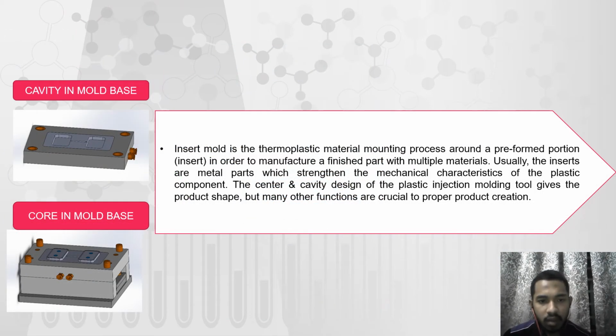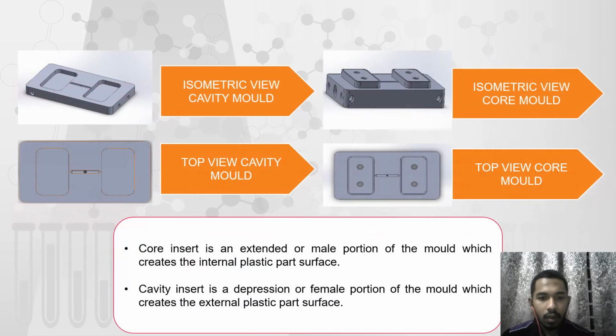Cavity in a mold base. Insert mold is the thermoplastic material molding process around a preformed portion, the insert, in order to manufacture a finished part with multiple materials. Usually the inserts are metal parts which strengthen the mechanical characteristics of the plastic component. The core and cavity design of the plastic injection molding tool gives the product its shape, but many other functions are crucial to proper product creation.